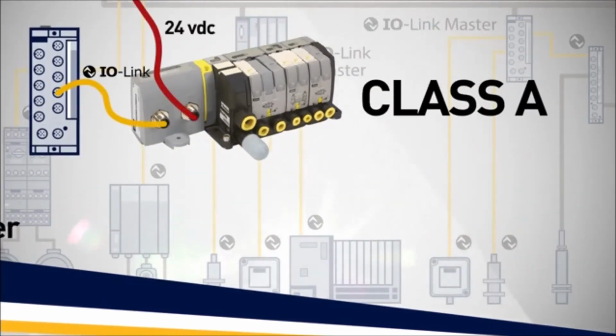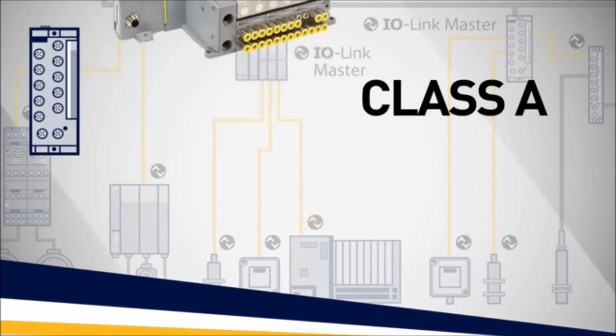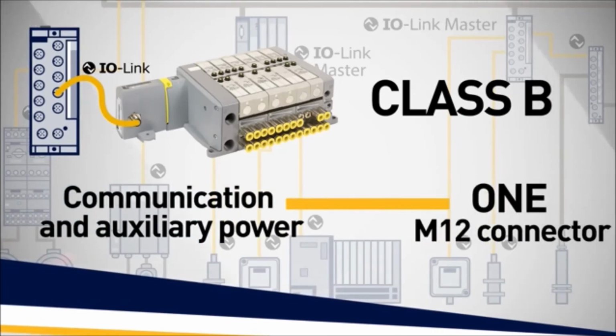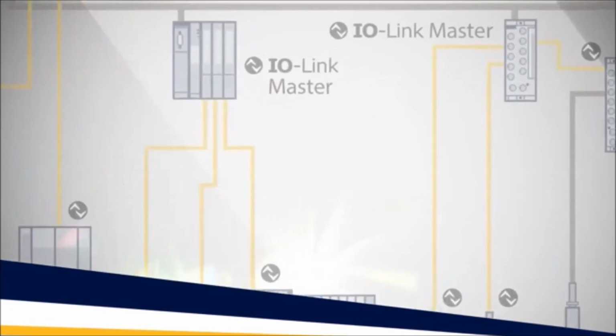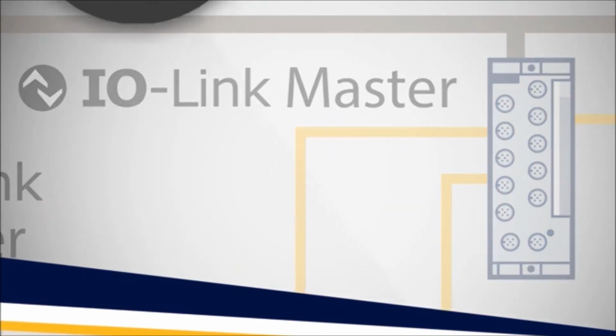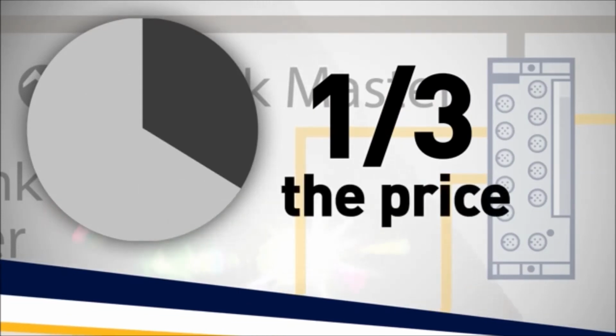Class A: communication and auxiliary power are supplied through two separate M12 connectors. Class B: communication and auxiliary power are supplied through one M12 connector. And we can just connect onto those free open I/O Link master ports to get our valve on the network at half or a third of the price of a node.